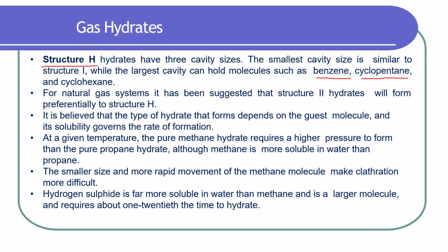Another thing to keep in mind, as we explained earlier, is that natural gas will form a gas hydrate based on structure 2 hydrate more than any other. So it's well accepted, and well documented in the literature, that normally structure 2 will be found in natural gas hydrate.